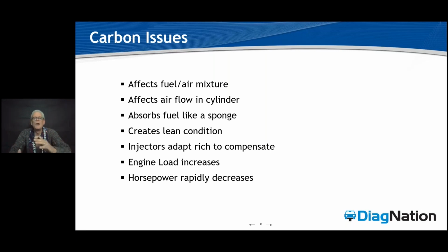Now in the GDI realm, there is nothing worse for carbon buildup or carbon problems for a GDI, or a high pressure diesel for that matter, than extended idle times. So when you think about the number of GDI vehicles that are sitting in traffic in our areas, going very short trips to work, these are the customers that are in deep, serious problems drivability wise with these issues, okay? Because the carbon in all cases is going to move baseline data in our OBD2 system and create the adjustments and the issues that you see on this current screen.